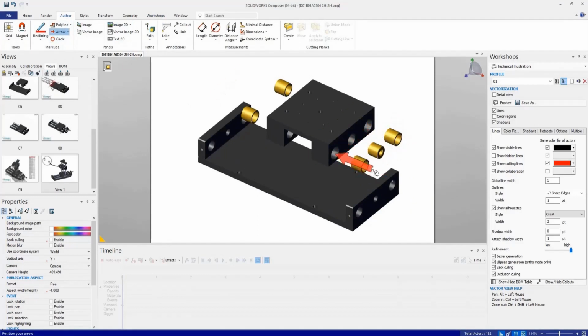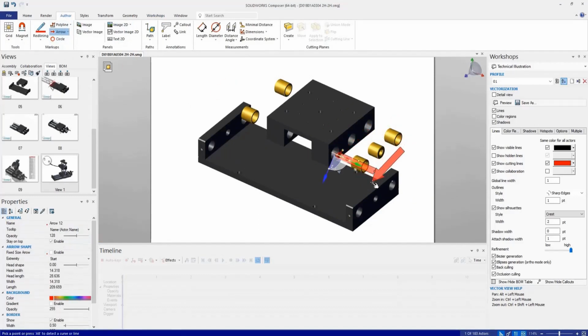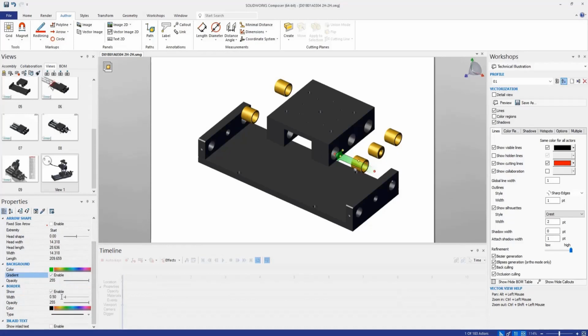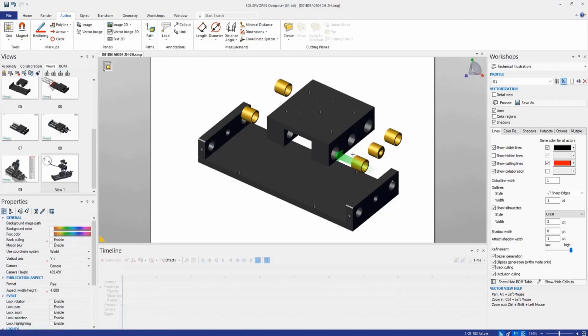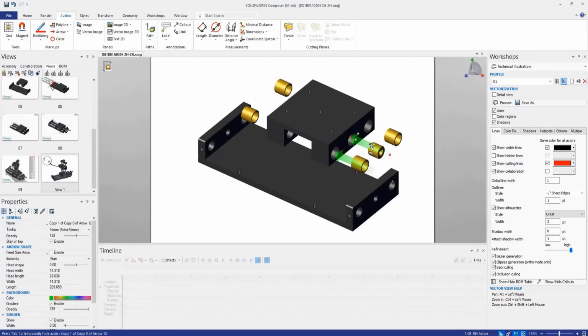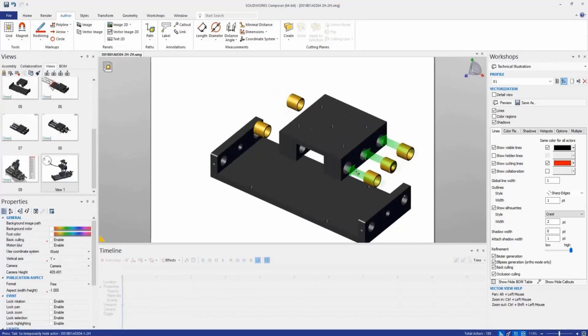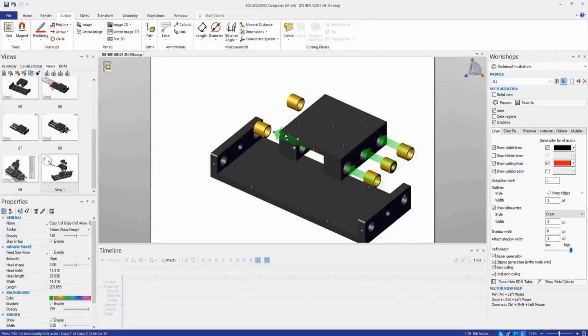For that point of view, we have the Author tool available, in which you can create arrows, circles, polylines, and other things as well. You can also generate the magnet line for your callouts. Here I can change the properties as per my need and simply copy and paste them to my other components. For the other side, I can again utilize this arrow by copy and paste and just selecting the extremity to end, so it will change the direction.